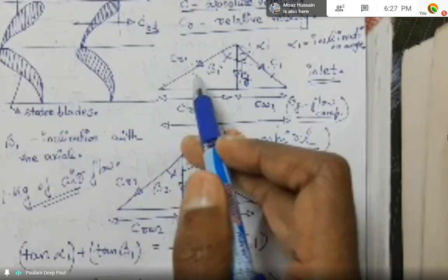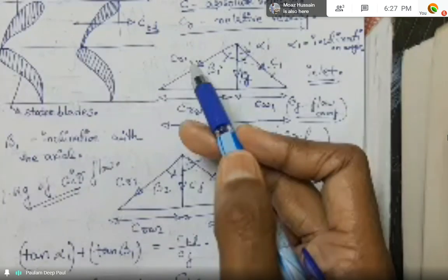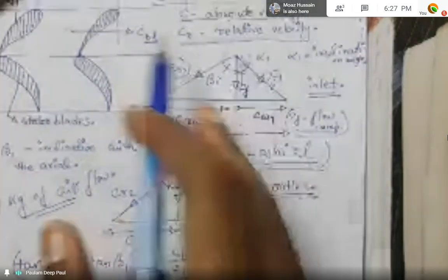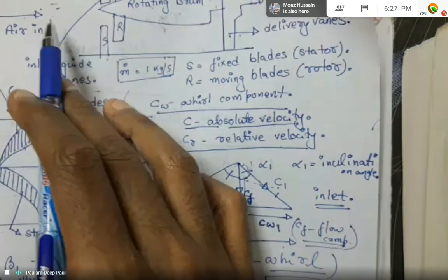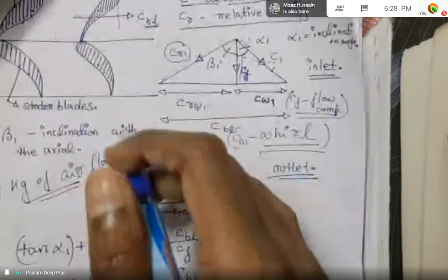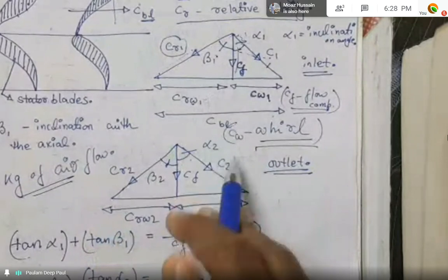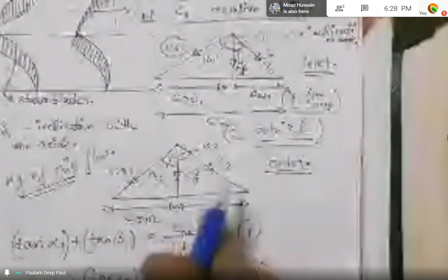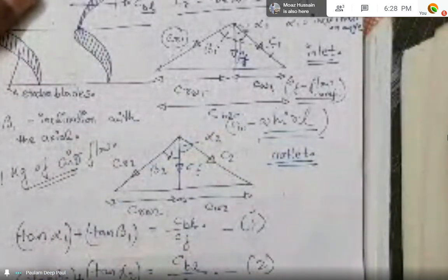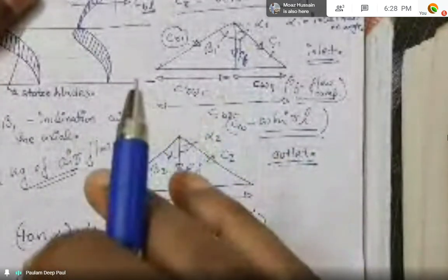This is the whirl component that has been given by the relative velocity that is arising due to the difference between the velocity of the incoming air, that is this or this, and the blade velocity that it is rotating with. So these are the two velocity triangles that you'll get once you start drawing it up, and just check for any irregularities or anything. Now from these two triangles, we will have simple basic geometrical constructions for the formulas.